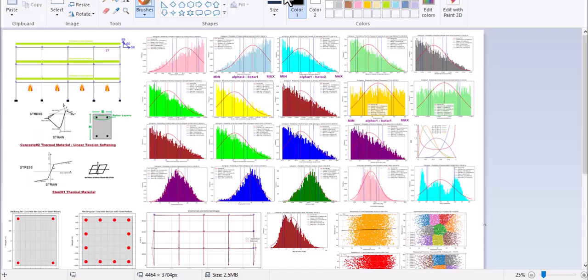So in uncertainty conditions, we're going to define each element and materials and also loads properties using beta probability distribution functions, with different alpha and beta coefficients, and run it 6,000 times, and then output the data such as displacement in x and y direction, and also different base reactions of these concrete frame structures.